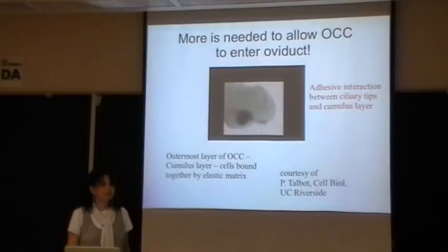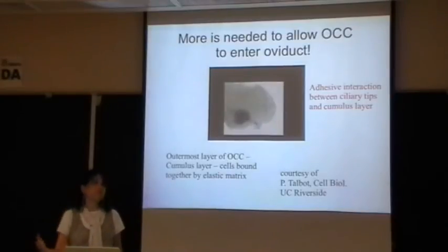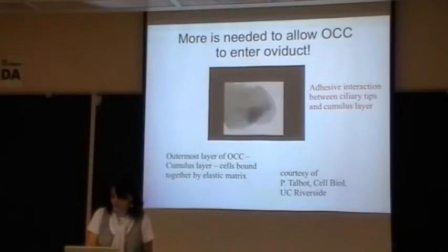Maybe you said this, but are the fluids in here characterized, the rheology of these? Probably not. You know, the thing is, it's nice, we all know Newtonian fluids, Navier-Stokes equations. We would like to understand viscoelastic properties. To say, even within a cell or within the cervix or so on, what type of model should we use? Is it an Oldroyd-B model? Is it a Maxwell model? It's probably something much more complicated, and that is still open for study. So I'll talk a bit today about some of the things that Mike was talking about yesterday and look at some simple complex fluid models.